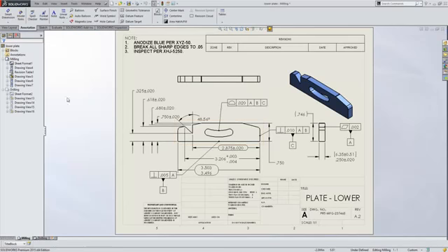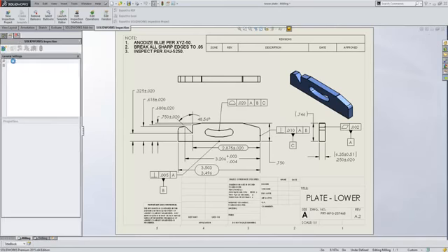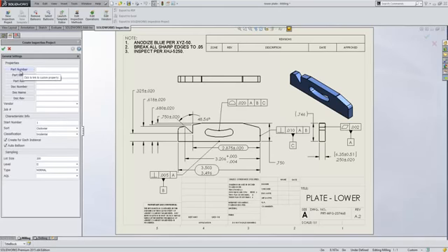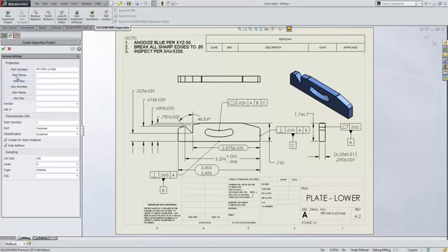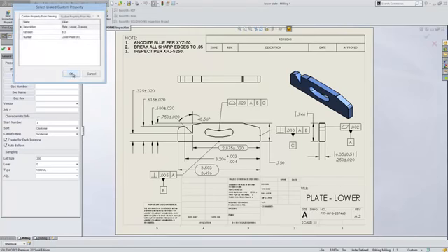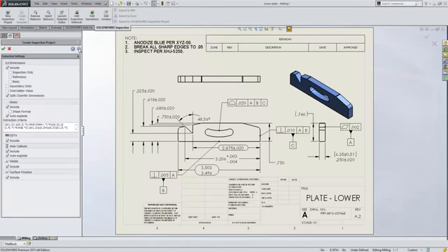If we switch over to Solidworks now, it carries its own Solidworks Inspection add-in here. So what we can do is we can create our new project from within Solidworks, again choosing our template. The difference here is that any information we want to pick up from the document, we can start to grab from the actual custom properties of the part or custom properties of the drawing. So we can directly fill that information in like so, and start to populate that a lot quicker really than we can using the OCR method in the standalone application.